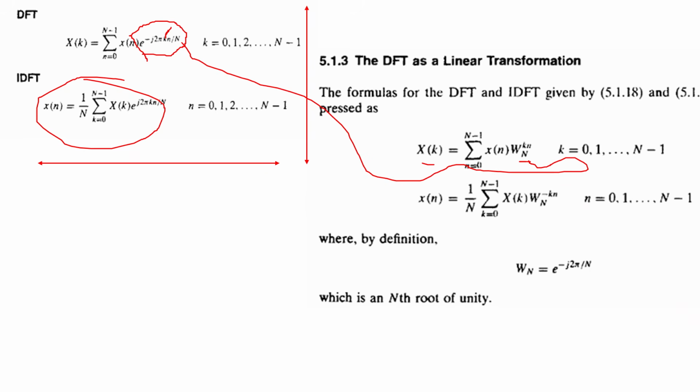And why are we doing this? Because if you see, the input is varying. Like suppose these are the sequence 1 2 3 4 for the input, with amplitudes suppose 1, 1, 1, and 1, or suppose any variable, 1 2 1, but these twiddle values are fixed values. So why calculate them always? In order to find the value of X of k, that is why we are replacing it with W and k.